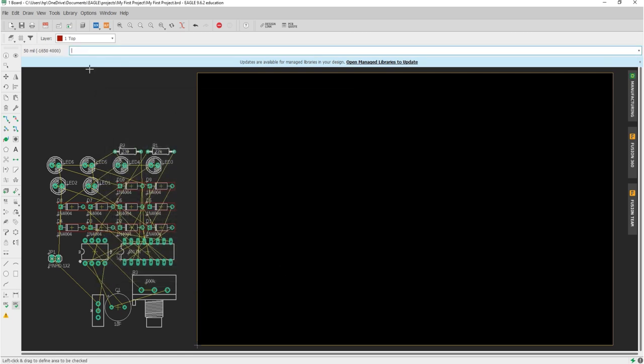The net classes feature lets you select different widths for each net. This is useful if you, for example, want your power traces to be thicker than your signal traces. In this example, we'll set up new net classes for our ground and VCC net. Then, we'll set the default width for all the other nets.